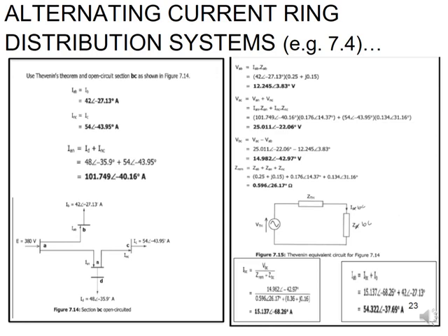You take that IBC, and you substitute it back into your system. The first place you can go to is that node at the top where you've got the IAB coming in, because you know you're going to have IB coming out as well as this IBC coming out. So you add those two together and you can get what your real IAB is going to be. Once you have that, then you can go to your bottom part of your circuit.